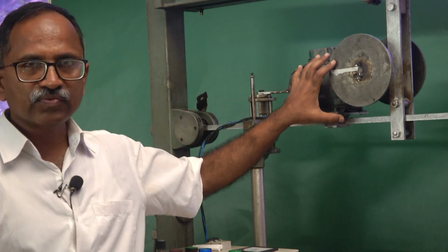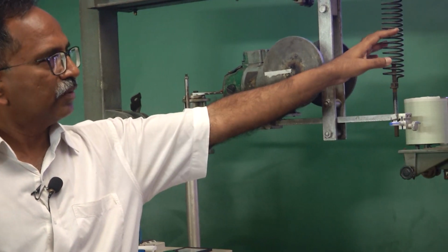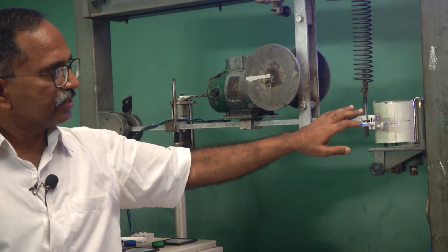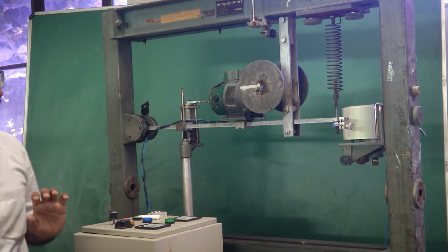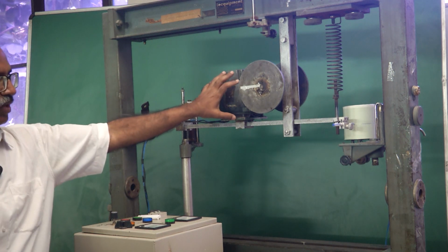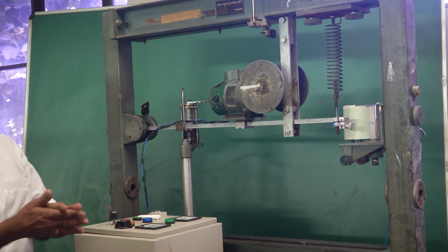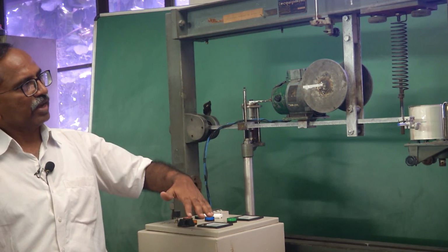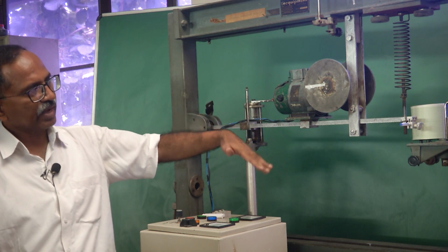Now, apart from this mass which is fixed at this location on the beam, the beam is hung by a helical coil spring, as you notice here. So, the spring is fixed at this end and it is connected to the tip of the beam at this end. Okay. So, this is the simplest of the vibratory systems, consisting of mass and spring. And unlike a typical spring mass system wherein we have a vertical translatory vibratory motion, this one is an angular vibration. Okay. So, the beam is swinging about this point. So, the beam executes an angular vibration.